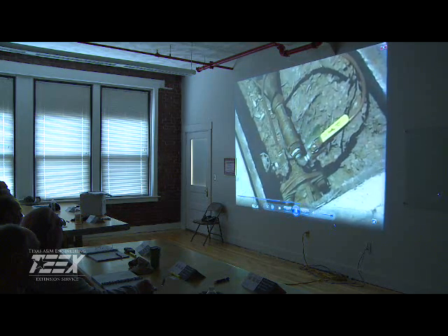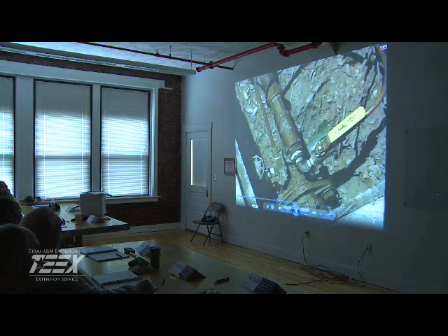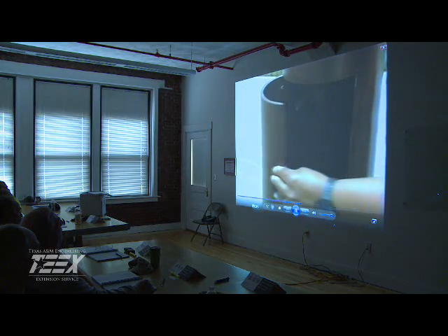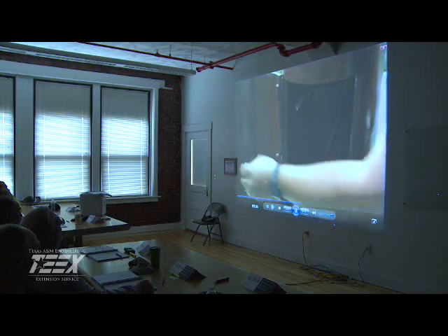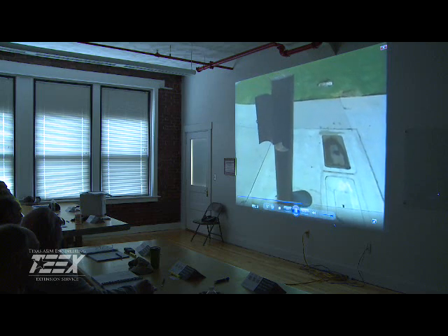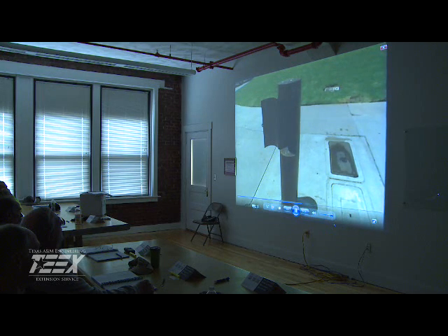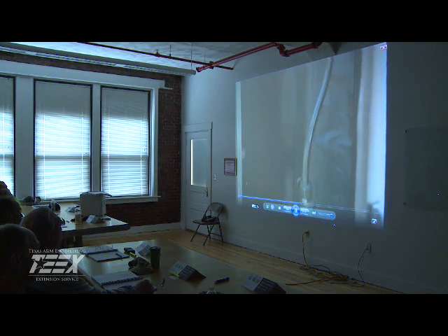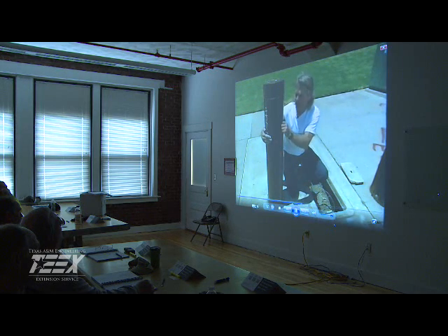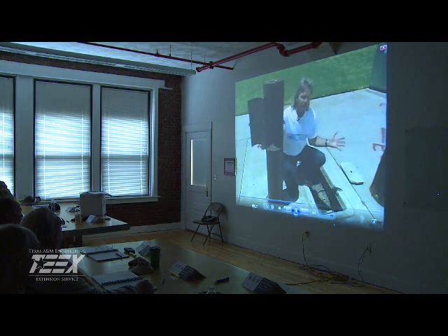I tapped in to the 2-inch, went under the sidewalk, and went up here and installed the shell here, with a gooseneck and a valve. And you close the cover, lock it up, and it's secure. So kids can't get into it or it can't get contaminated in any way. And the dedicated sampling stations are working.